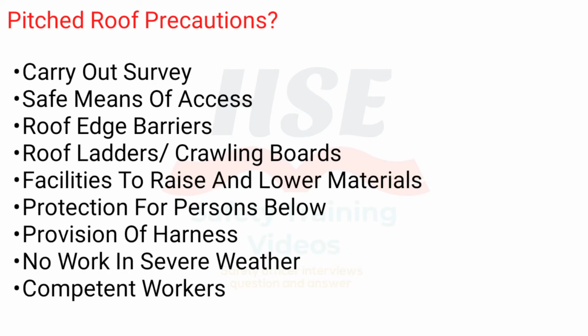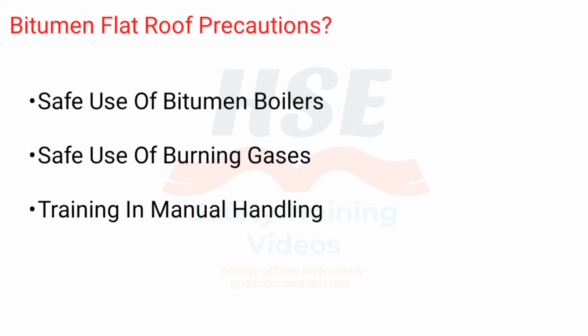Pitched roof precautions. Carry out a survey. Safe means of access. Roof edge barriers. Roof ladders and crawling boards. Facilities to raise and lower materials. Protection for persons below. Provision of harness. No work in severe weather. Competent workers.